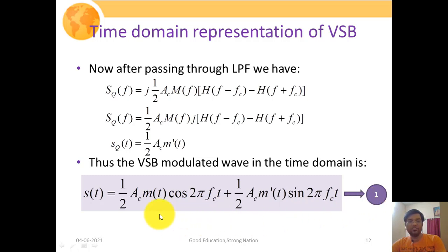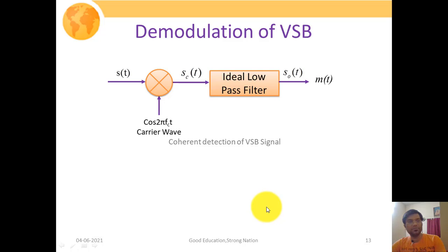We have evaluated the in-phase component and the quadrature component via the previous analysis. Now, how are we going to perform the demodulation of the VSB-SC signal? The s(t) signal is the same that we evaluated on the previous slide. We are talking about the coherent detection technique, so we use the same carrier frequency as at the transmitting side.